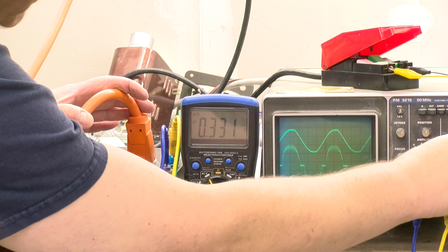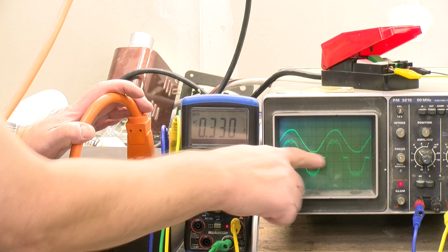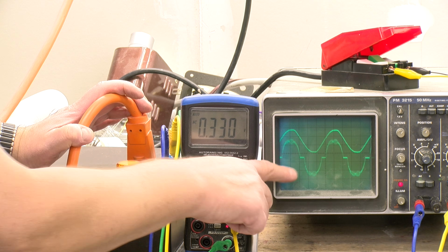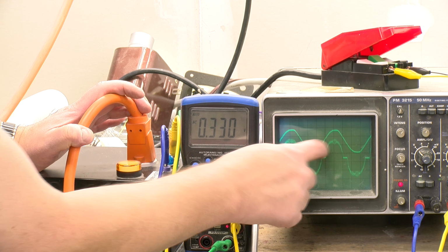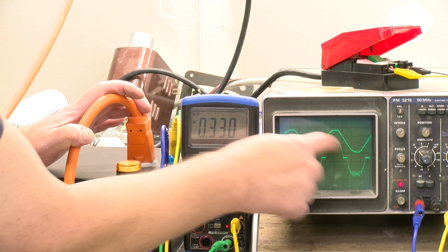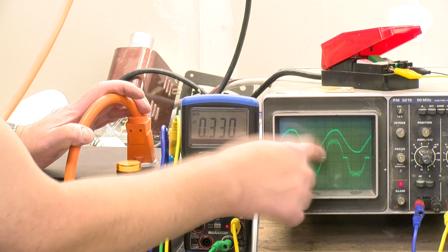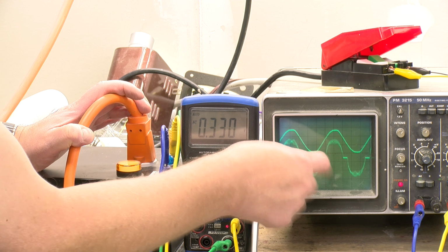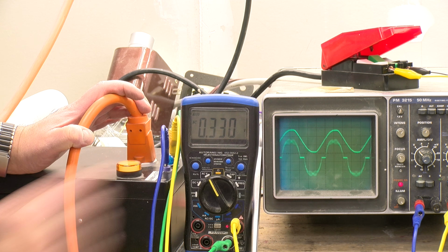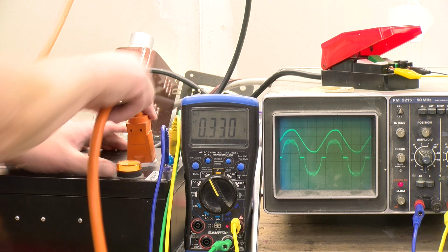I don't remember which, but clearly some sort of circuit in there that's trying to spread out the middle current pulse to make it resemble a sine wave considerably better than those very peaky ones and reduce the harmonics. So they've done a good job.